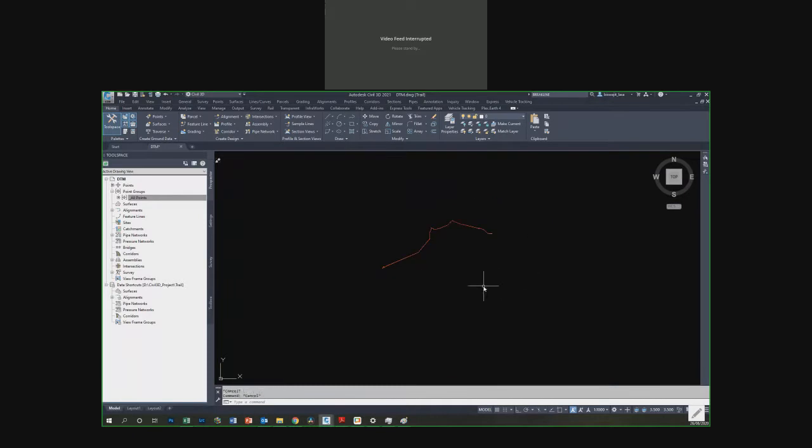For that you have a command, flatten. Select everything. This will take some time, I guess. Always select no here, and then leave the drawing for a couple of minutes. It will keep the xy same and the z values to be 0.